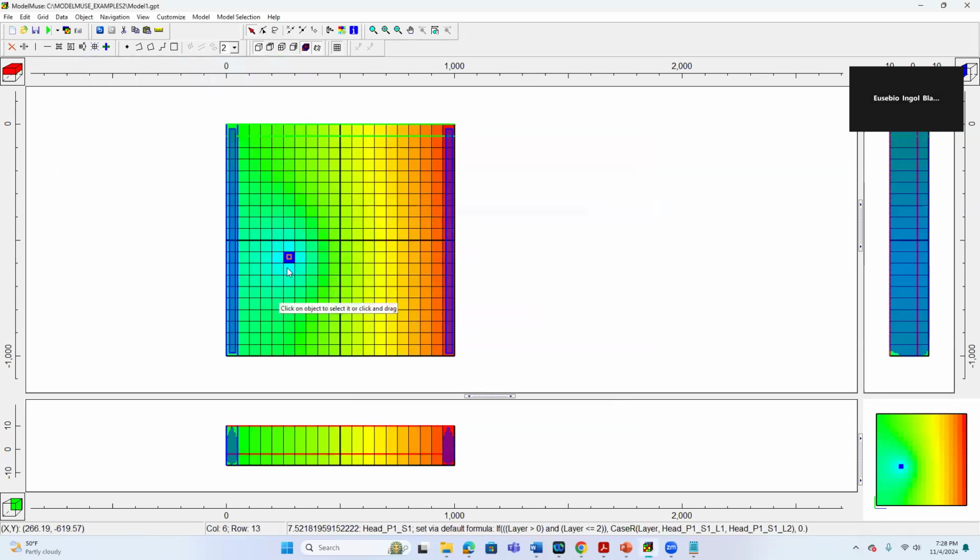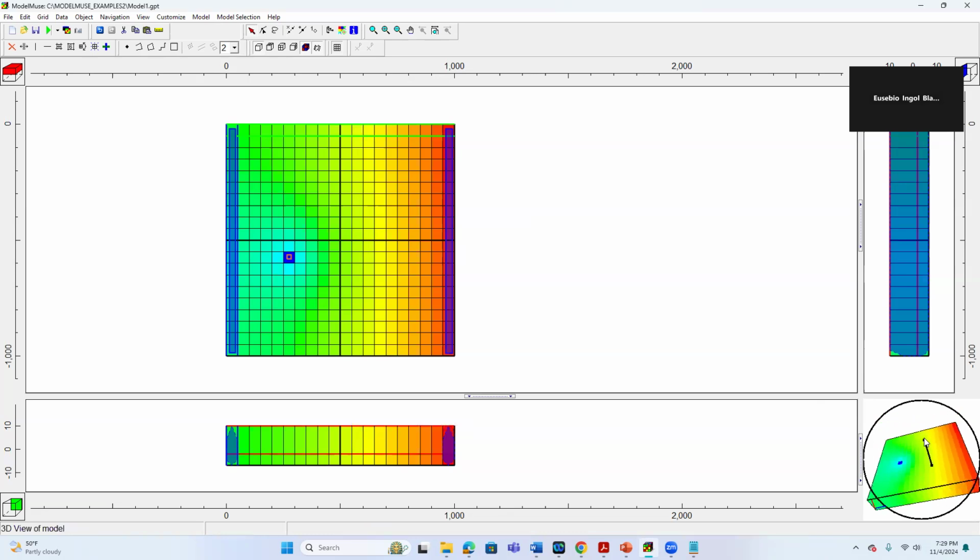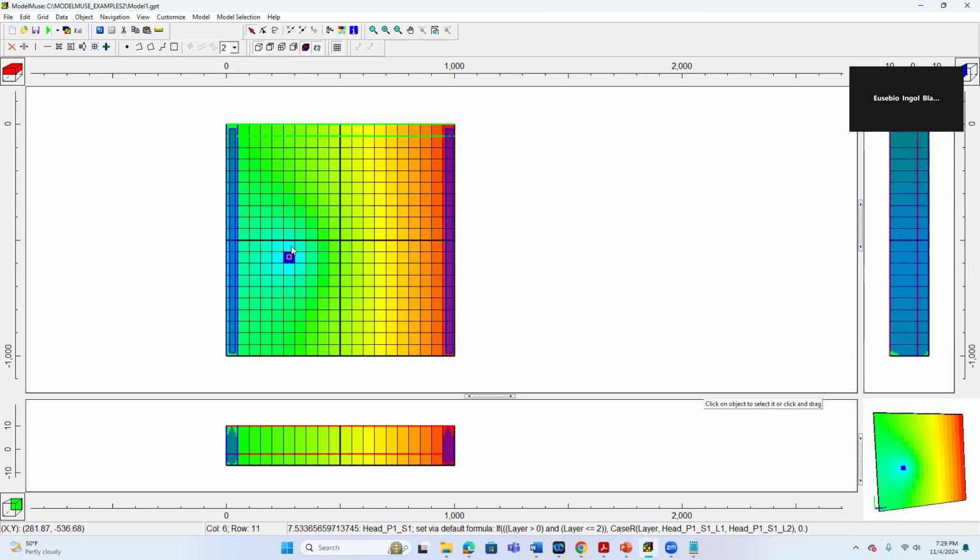Now you see here how this part, the region, is going to change, because we have the 20 liters per second, right? Or 0.02 cubic meters per second. We are going to see the contour levels in order to see the difference. Look at this model in 3D. It's very interesting, this area. We see the depth and the drawdown. Do you remember the drawdowns that we studied in class? We are going to see how the contour levels change here.